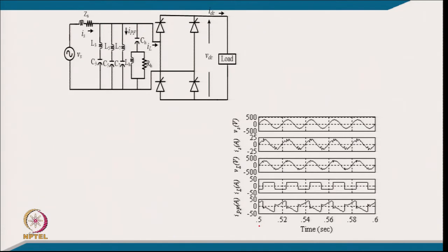So, these are typically the non-linear load with the thyristor and constant load current, and this is the passive filter we are designing, I mean for third, fifth, seventh and high pass. And after putting in the values, these are the typical waveforms of supply voltage, then supply current, the load voltage, and then we have the load current and the passive filter current.